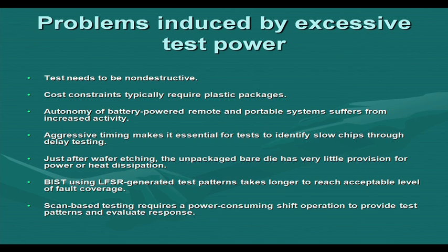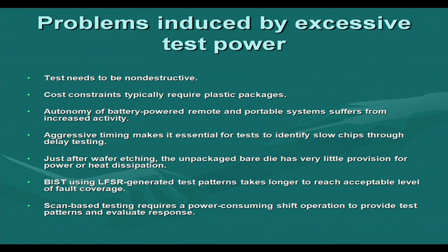Then, if we look into the test techniques that we have seen so far, like BIST, in built-in self-test we generally use an LFSR to generate a large number of patterns. In a fault simulation process, we can run the LFSR, see the patterns that are getting generated, and try to see what faults are getting covered by individual patterns. Then, after running the LFSR for a good amount of time, we may reach the sufficient level of fault coverage that we are looking for, and then we stop the LFSR. So, the LFSR has to be run for so many cycles.